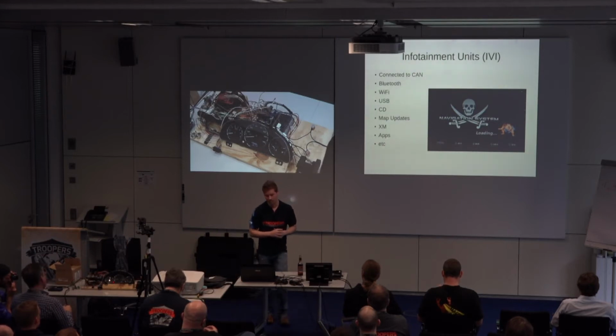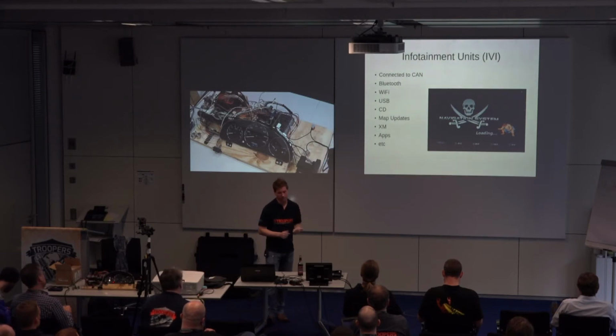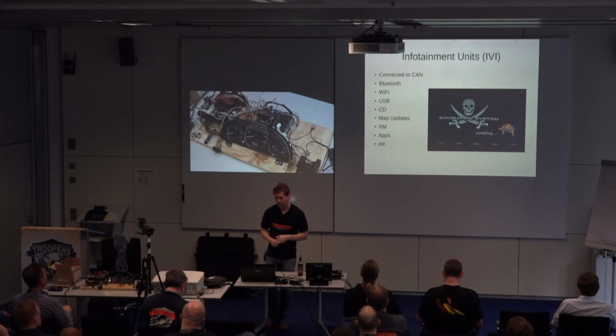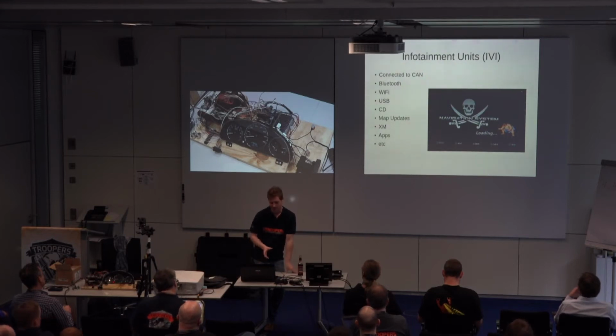2009, and I can't remember actually what the nav system was in that guy, but that was running a Hitachi SH4 processor, which is the same one that runs in Dreamcast. So that was a little bit different, but it was still Windows CE, and it was pretty easy to manipulate and hack. I basically used the update method to do that. The update method would just be the method it typically uses to get map updates, and it also had system DLLs in it, and a really, really simple check to make sure you didn't mess with it, which was an MD5 hash. So you just mess with it and then update the MD5 hash, store it on the same CD. So they're not terribly hard from a security perspective to manipulate.